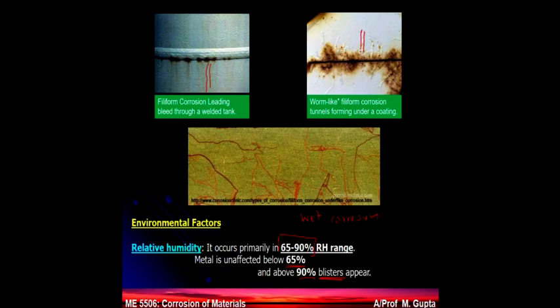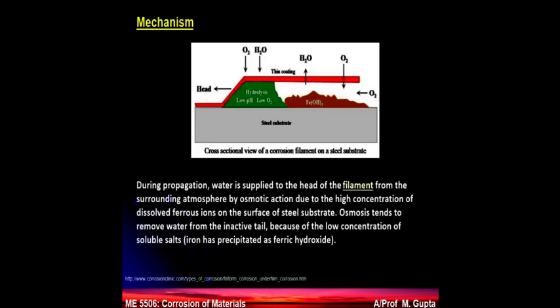So if you look at a magnified view of the mechanism, you see there's a breach here. So I will say breach of coating. That means the coating is damaged here, and then when the coating is damaged, you have the oxygen differential from this point to this point, and slowly the corrosion moves in this direction. So it has a head and it has a trail.